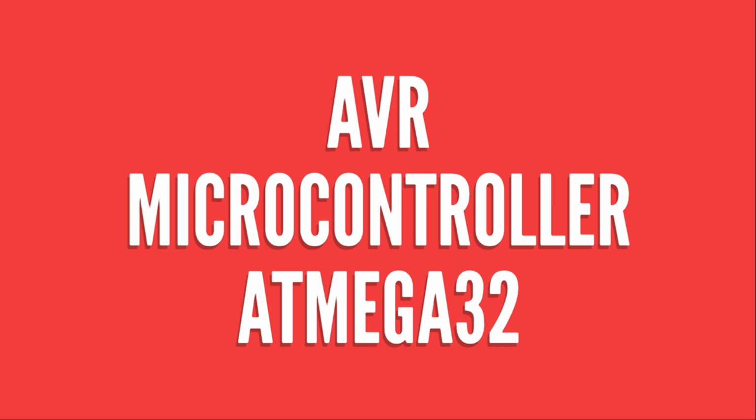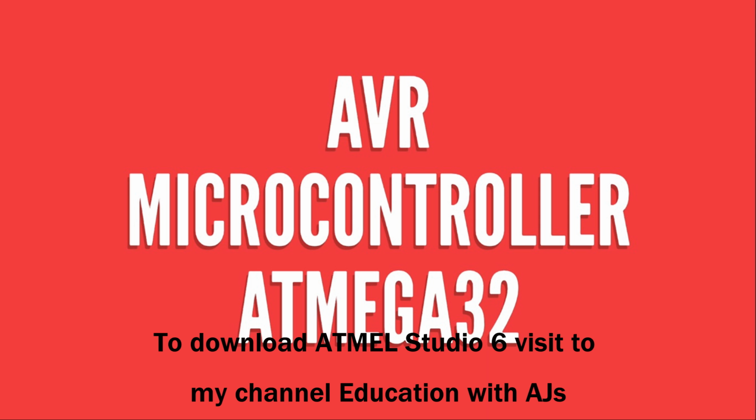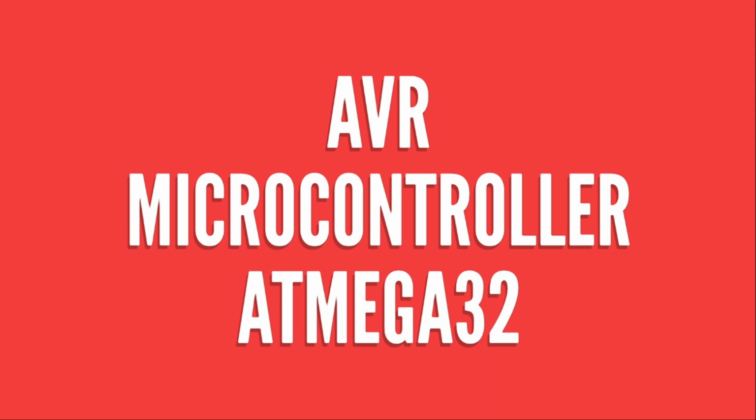After the difference, we are moving towards AVR. The creator hasn't given any specific full form, but we commonly say AVR stands for Alf and Vegard's RISC. We are using ATMEL Studio 6 as our platform and the language is C. AVR is an 8-bit microcontroller. Specifically, the ATmega32 has 32 kilobytes of flash memory, 2 kilobytes of RAM and 1 kilobyte of EEPROM.